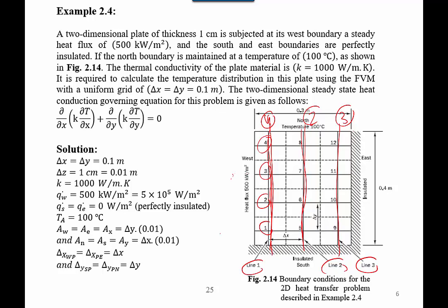At the west side it is a boundary condition with this flux, and at the east side there are the temperatures T5, T6, T7 and T8, which are also unknown. The variables for matrix number 2 are T5, T6, T7 and T8, and the variables for matrix number 3 are T9, T10, T11 and T12.